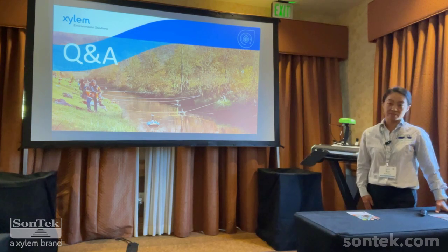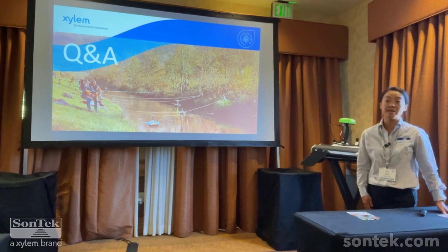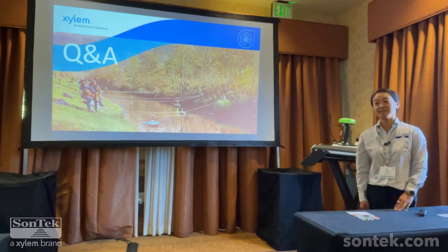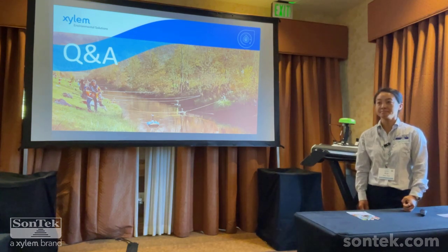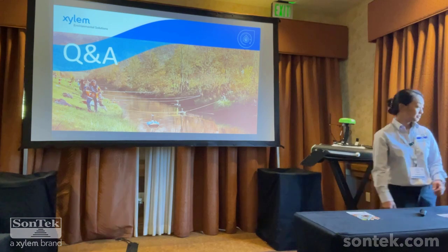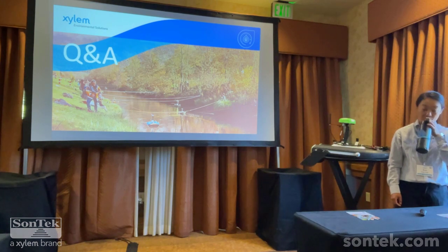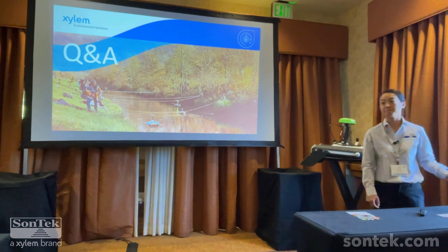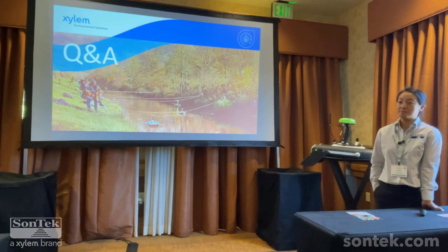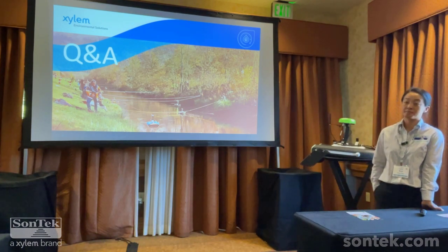If you're using the M9, which is our larger ADCP, it's a little bit of an older platform, and that actually has two separate softwares, but the same instrument, same idea. And there's some post-processing that's built into RSQ, the newer software. It's not available in River Surveyor Live and River Surveyor Stationary Live, which are the M9 softwares. But after the measurement, you need to use River Surveyor Live or River Surveyor Stationary Live for an M9 measurement. But after the fact, you can open them in RSQ and do some of the post-processing that's available in there, and look at the data there.